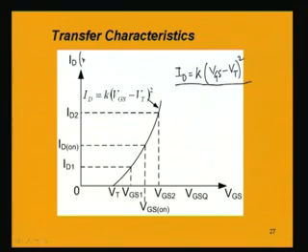That means, on the same axis as we have drawn right now between ID and VGS, we will be taking the same axis, ID and VGS. ID is in milliampere, VGS is in volt. Start with the threshold voltage, that is the voltage between gate to source till when the drain current is 0. So, this is the point, say. One point is on the VGS axis, which is the threshold voltage.